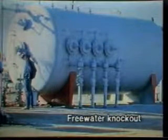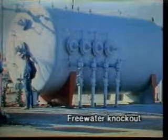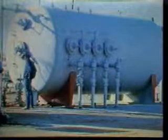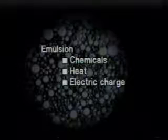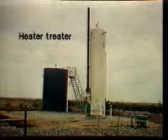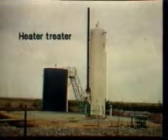A free water knockout is a simple separation vessel located along the flow stream, in some cases upstream of the separator, where the oil and water mixture is allowed sufficient time to separate. A more difficult separation problem arises when the oil and water are produced as an emulsion. We may break the emulsion and thereby separate the oil from the water by adding chemicals, by heating the emulsion, or by causing an electric charge to pass through the emulsion. Treating vessels utilizing more than one treating process to attack particularly stable or tight emulsions are common.